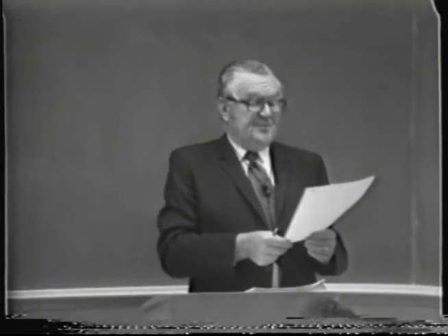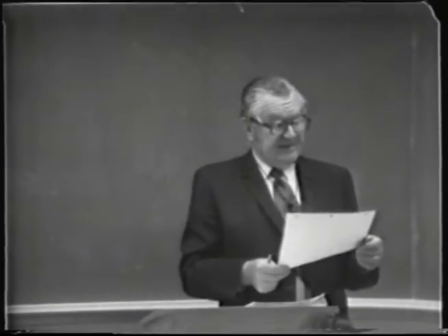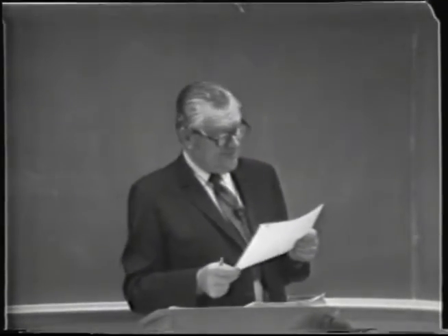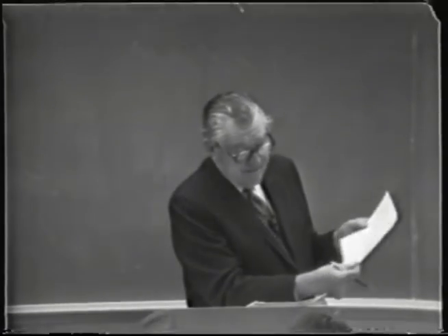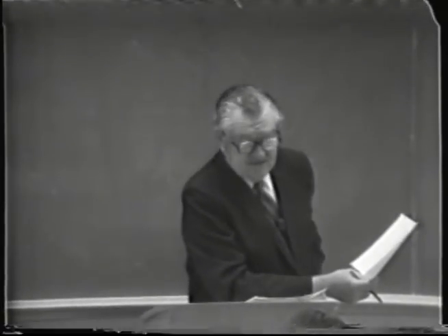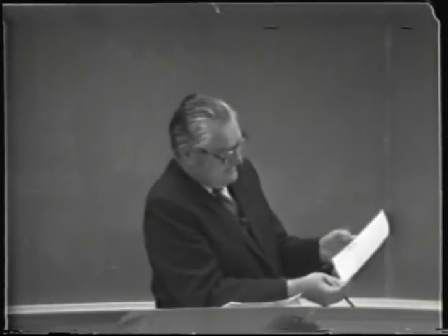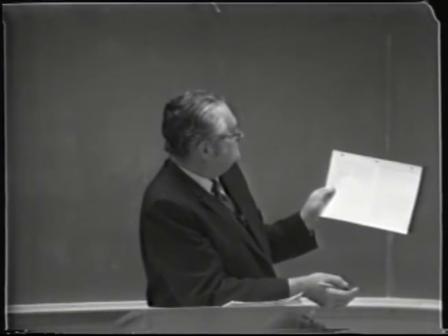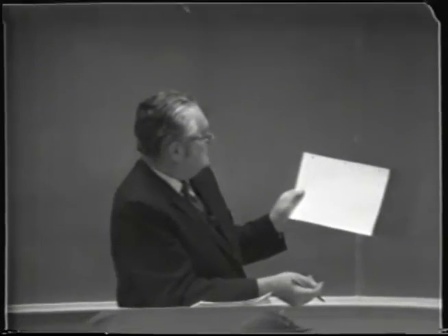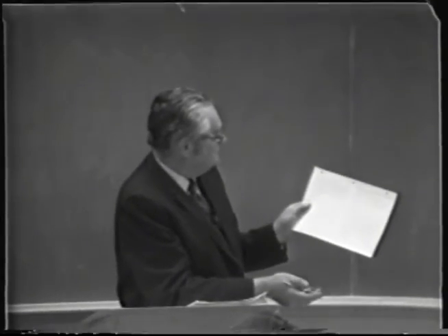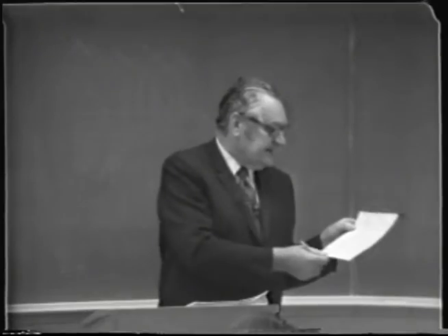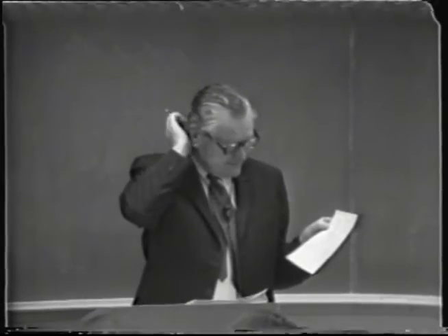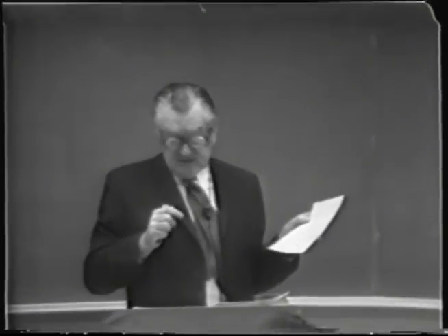And I might point out, though, that the main application of thermal compression, oh, excuse me, not in distillation, but in evaporation, is illustrated by this figure 1442 on the left, which shows the vapor recompressor over on the left here, which is put in there entirely for the purpose of economizing on the heat or the steam required.